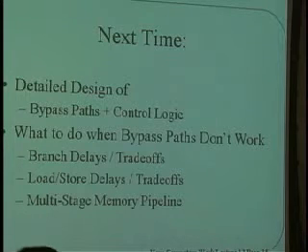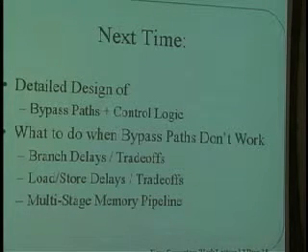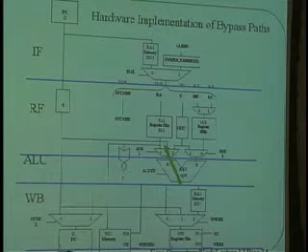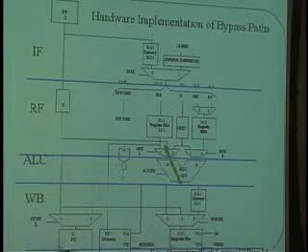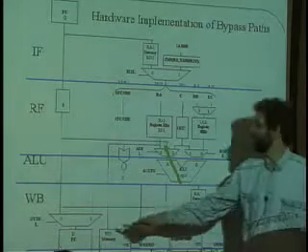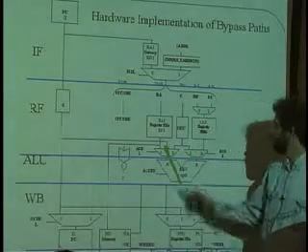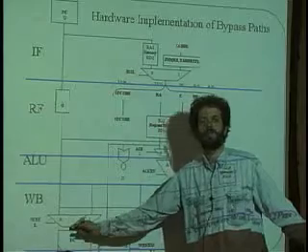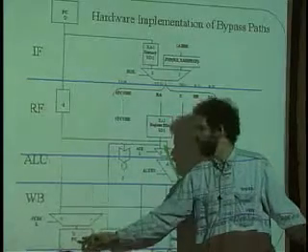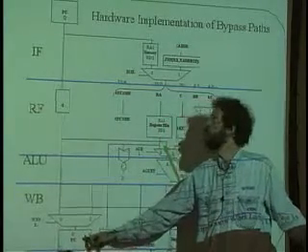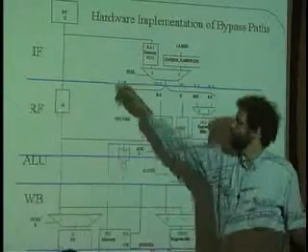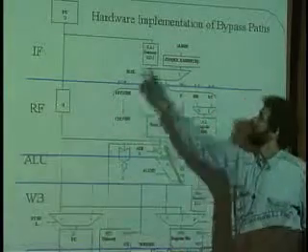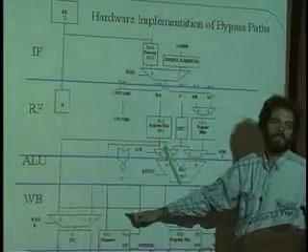And guys, get this. Think about what happens. Let me just get you started on thinking about this. What happens when you do a branch? When you do a branch, the PC gets updated with a new opcode, right? The ALU output goes to here, and the PC, instead of choosing this, chooses that. Okay? So we get a new PC in here. How long does it take before the new PC gets back down here? 1, 2, 3, 4 more clock cycles, right?